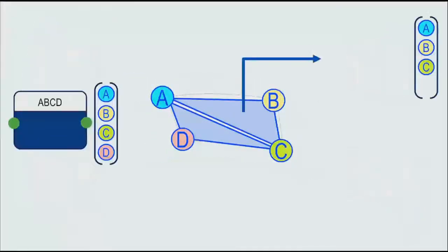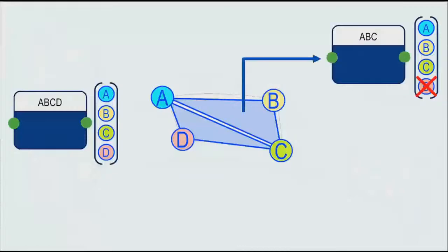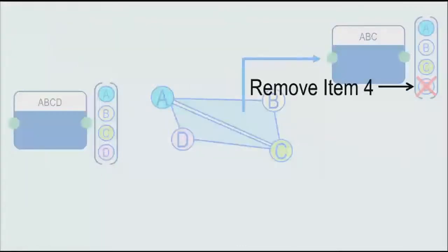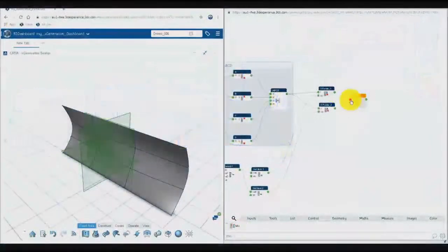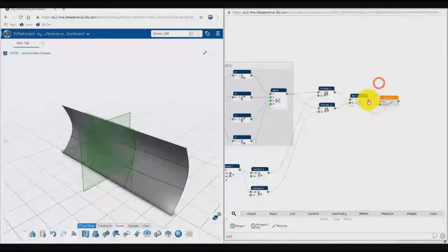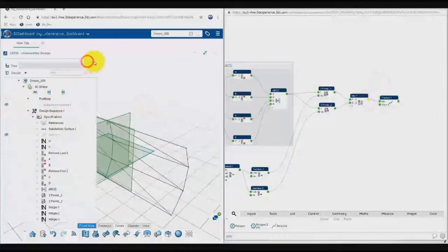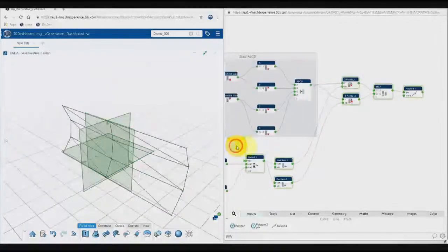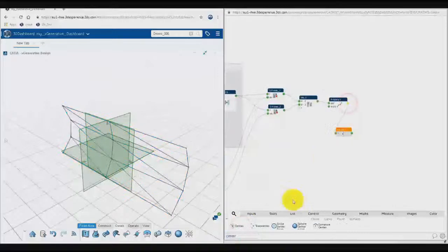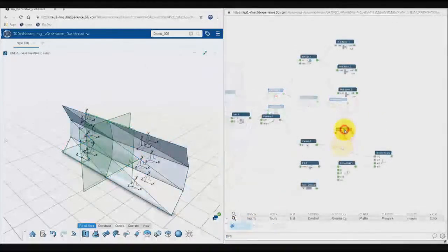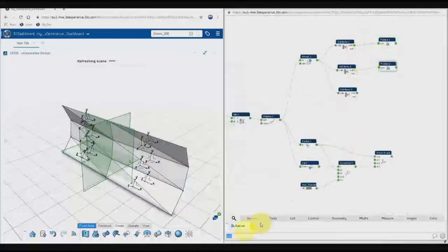So we'll walk you through in X generative design how to take a surface and create a triangle pattern on that surface, using a subdivision surface as an input just to test our model. So through list manipulation, we come up with the triangularization pattern. We can control the polylines and change them back and forth, change the orientation back and forth. We have axis systems that will anchor our engineering templates.